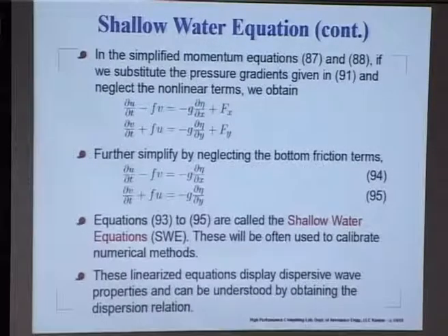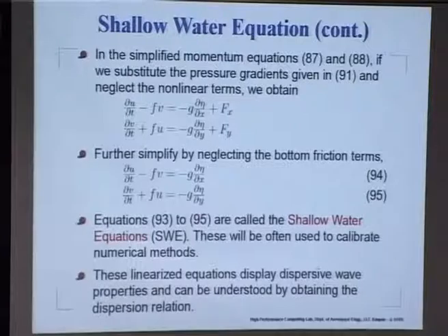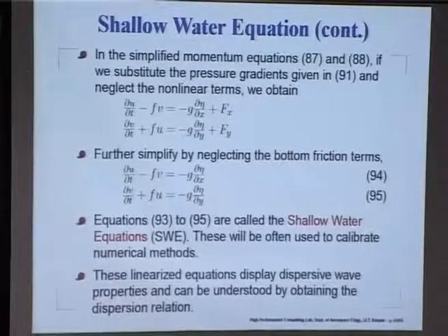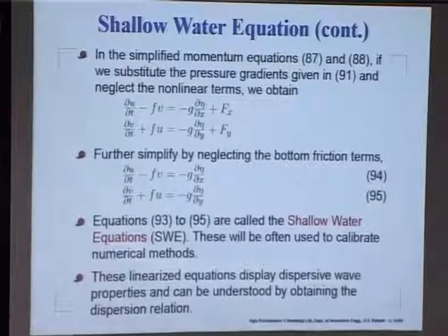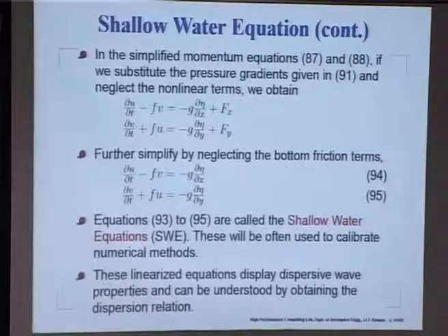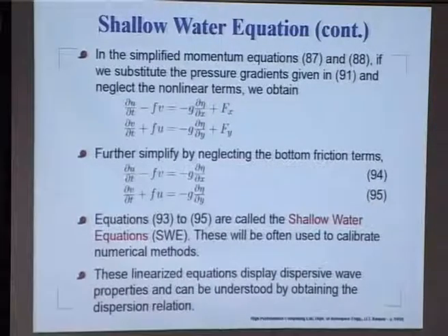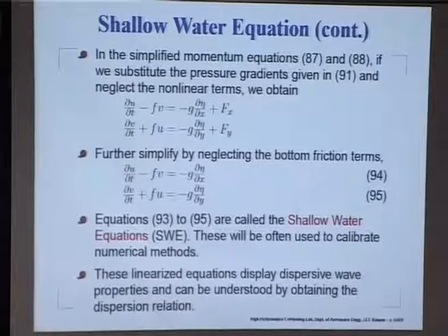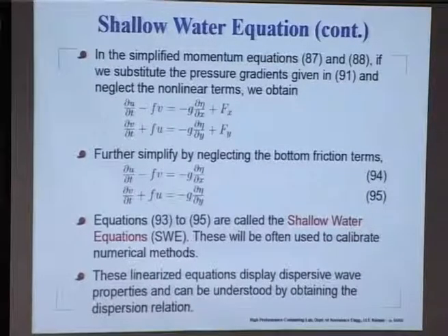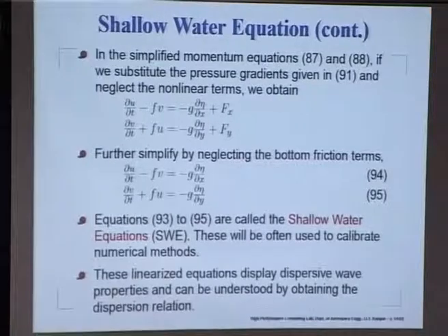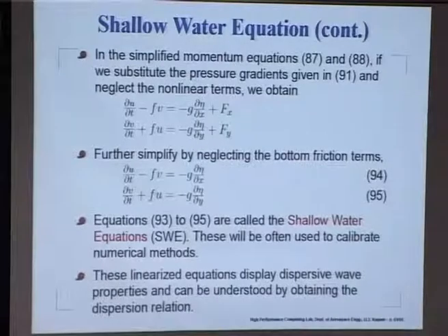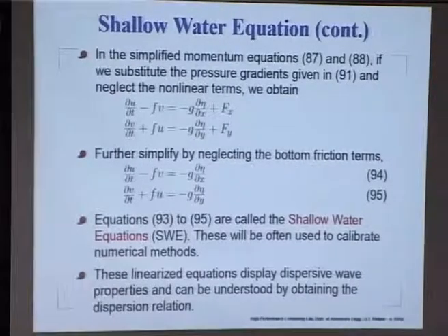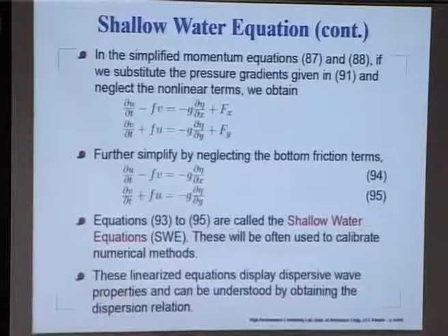Now, looking at the momentum equation, we have replaced del p del x and del p del y by these wave elevation terms, and these are of course our bottom friction terms. If we neglect those bottom friction terms, we get this, and what have we done here? In expanding the substantive derivative, we have also omitted those nonlinear terms, right. The nonlinear terms were there, like u del u del x, v del u del y, that has been omitted here, and same thing about this.